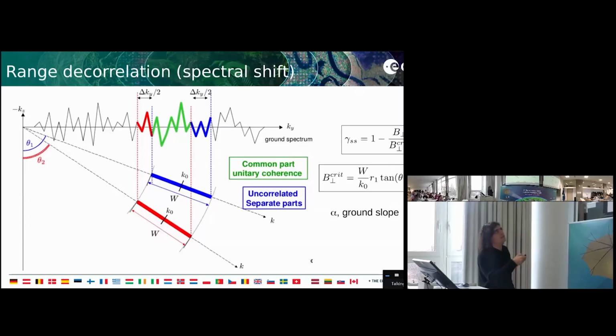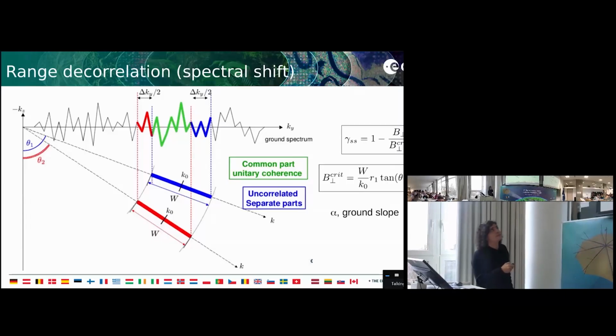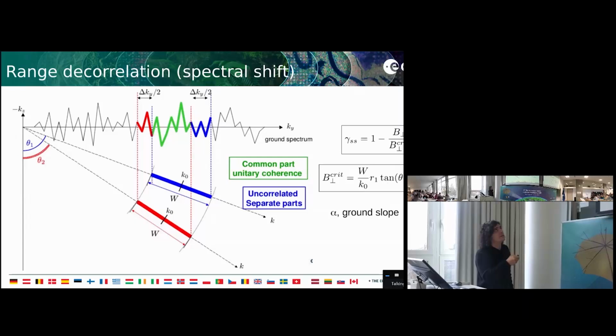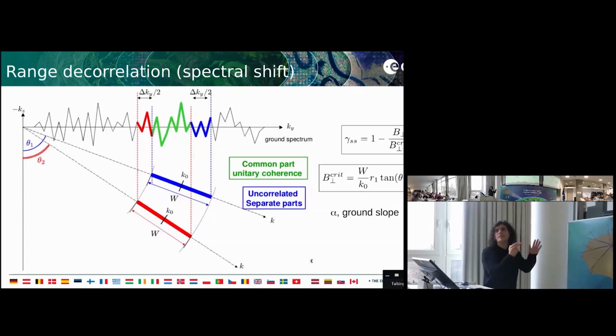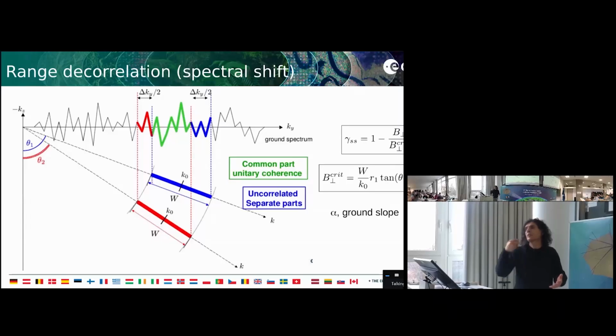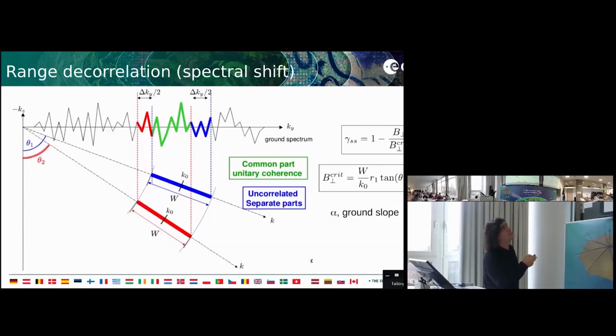So you are selecting spectral bandwidth, spectral slabs over a specific spectral domain. And when you do this, you are sampling the response of your environment over the ky axis over slightly shifted domains. And when you observe a natural environment, which is affected by speckle, if you apply a Fourier transform to speckle, it is still speckle, it is still not correlated. This means that you are selecting parts of the reflectivity of the environment that are not correlated.